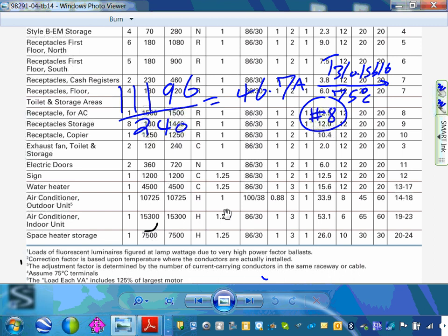So where would that be? Number 8 is right here. Number 8, 40. Okay. Now next, take number 8. How much current can number 8 carry? I think it's here, THHN. Under the 90-degree column, 55. Do you have 55 here? Oh, here.